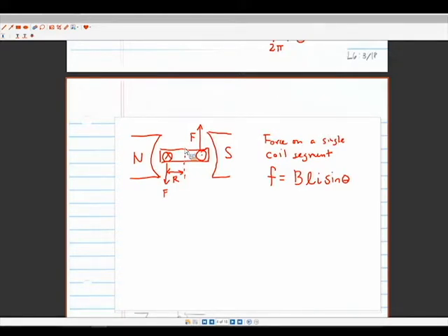So engineers know physics pretty well. They make sure that the current is running perpendicular to the magnetic field for the most part, because that's when you're going to get the most amount of force out of the system. That's when you get the highest energy transfer. So in this case, for all motors you'll see, really, unless there's some special cases I'm not really too aware of, this is going to be